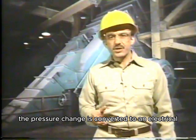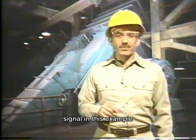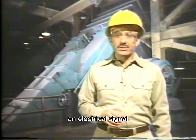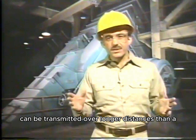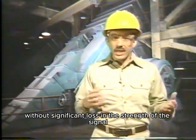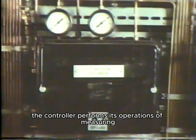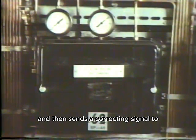The pressure change is converted to an electrical signal in this example because the controller is at a remote location. An electrical signal can be transmitted over longer distances than a pneumatic signal without significant loss in the strength of the signal. The controller performs its operations of measuring, comparing, and computing, and then sends a correcting signal to the final control element.